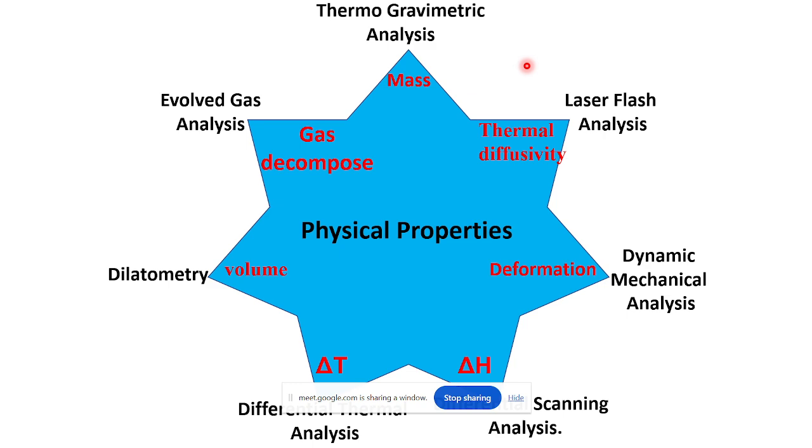Usually you need to perform at a lower temperature rate to probe deeply. Sometimes if there is a very small component, you may skip it if the rate is very high. If the rate of increment of temperature is very high, it may be skipped in your thermogram. So it's better to do the test at 10 degree centigrade or 5 degree centigrade per minute.